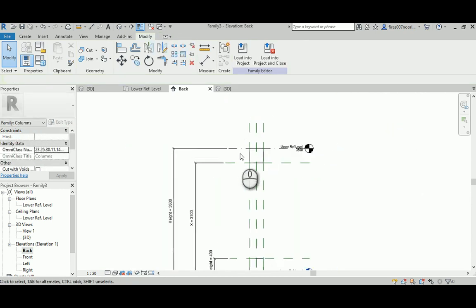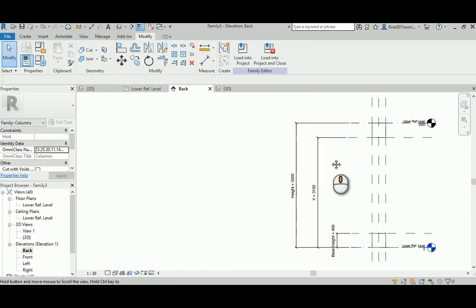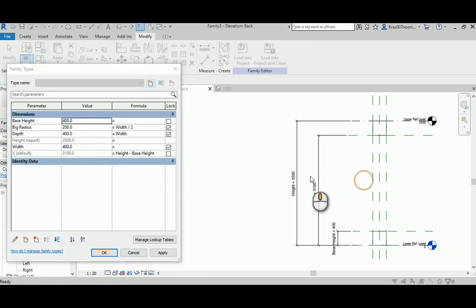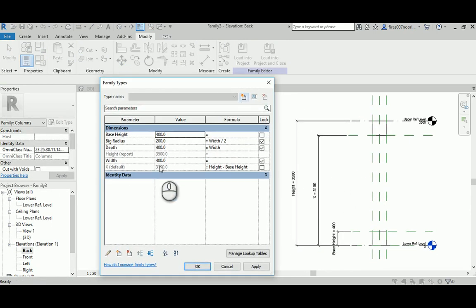See, beautifully working. And again, what just happened is that when I created the height, this one, it is actually measuring the distance from the upper reference to the lower reference, which the relationship can be different from one column to another, even if you are designing a type. So that's what we call an instance parameter. They can be the same thickness, the same everything, except this guy, which could be different depending on the height of the slab.